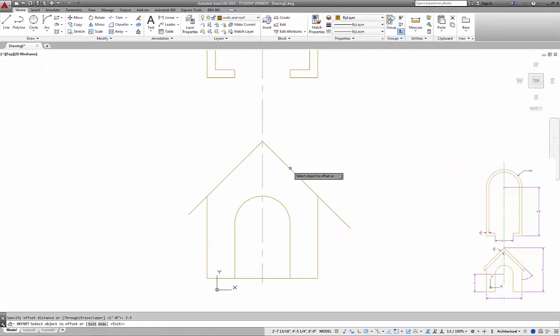We're going to offset for the fascia here. So the fascia board is now offset, and we will offset again, this time 6 inches, and this is going to be for the overhang. And that's basically a good practice to have for drip edges.